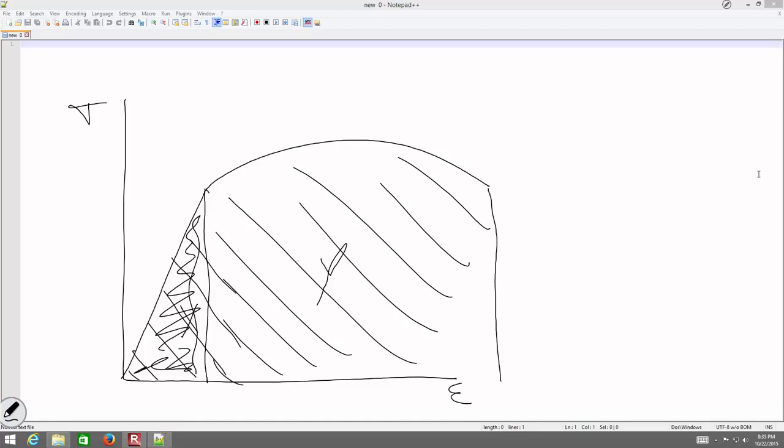Because design using ductile materials is limited to the elastic region where there's little difference. We don't want to take something beyond that, into the plastic region, because then we're getting crazy deformations. We don't like big deformations. We want to stay in the elastic region, and in that region they're both the same exact curve, so it doesn't matter which one you say you're using. They're going to give you the same result.